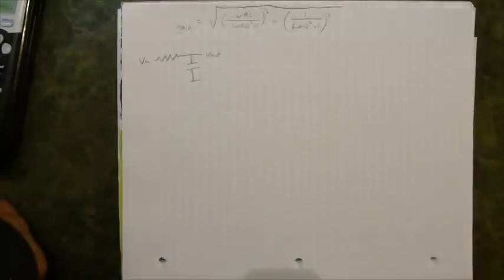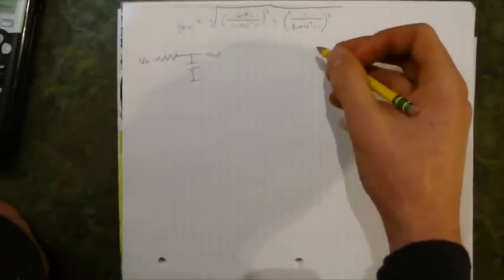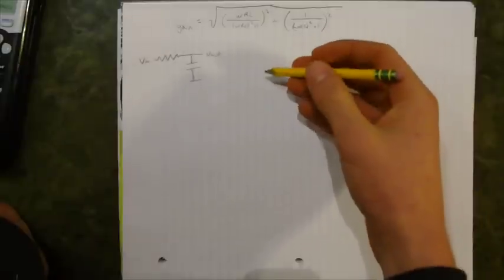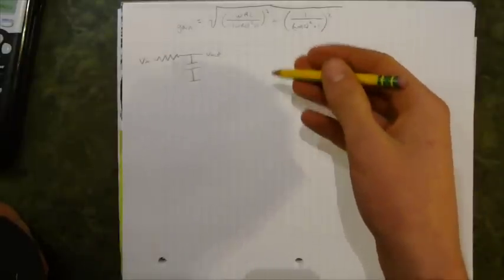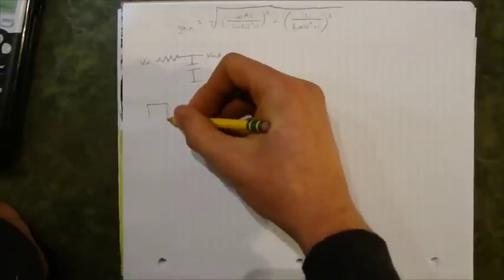This equation is in terms of omega. So we are trying to filter out the higher values of omega, which will be the higher harmonics of the square wave, and we're trying to attenuate those, or retain the fundamental frequency of the square wave, and that is the output frequency we would like. So our input waveform is going to look like this.